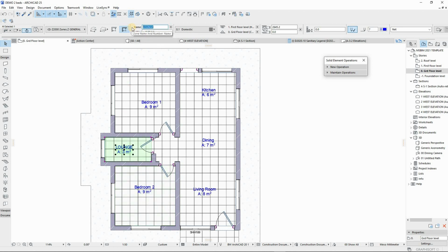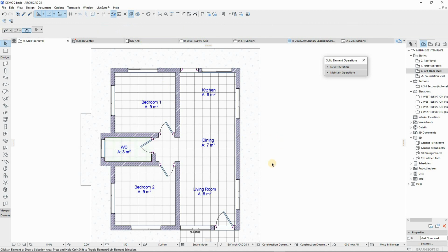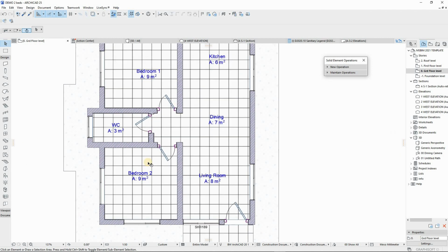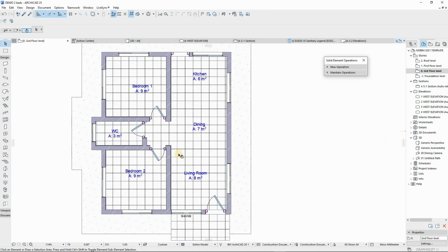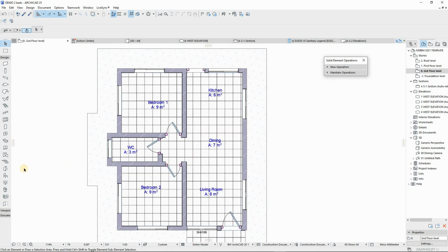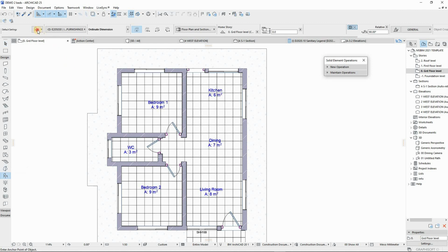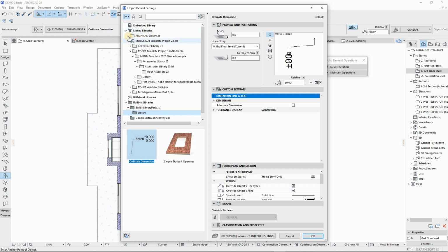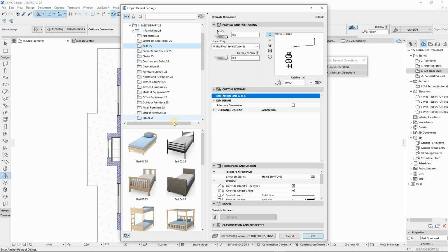This will be the bath and toilets. Perfect. So to place objects, furniture, I think let me skip that because it's straightforward. Or just place the common ones. Go to objects, then I'll go to the ArchiCAD library 25, then basic library. Let's open furniture, start with beds.